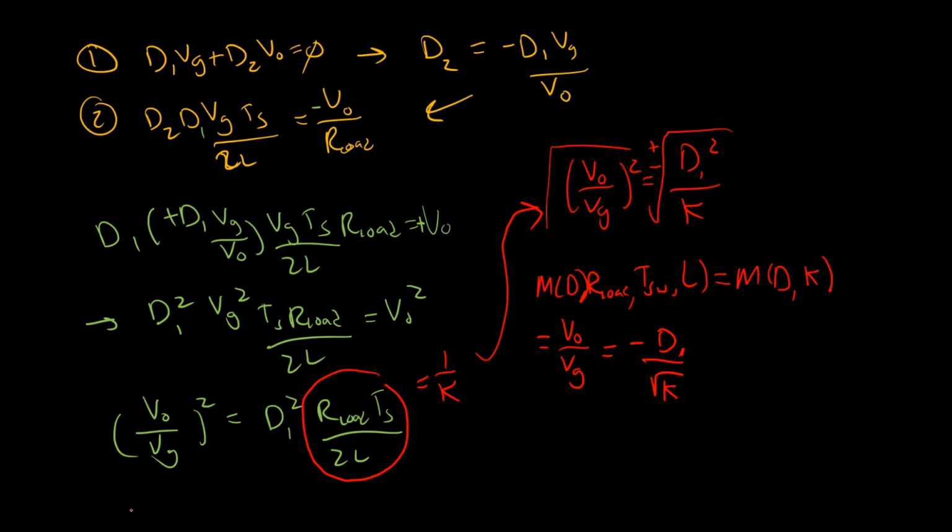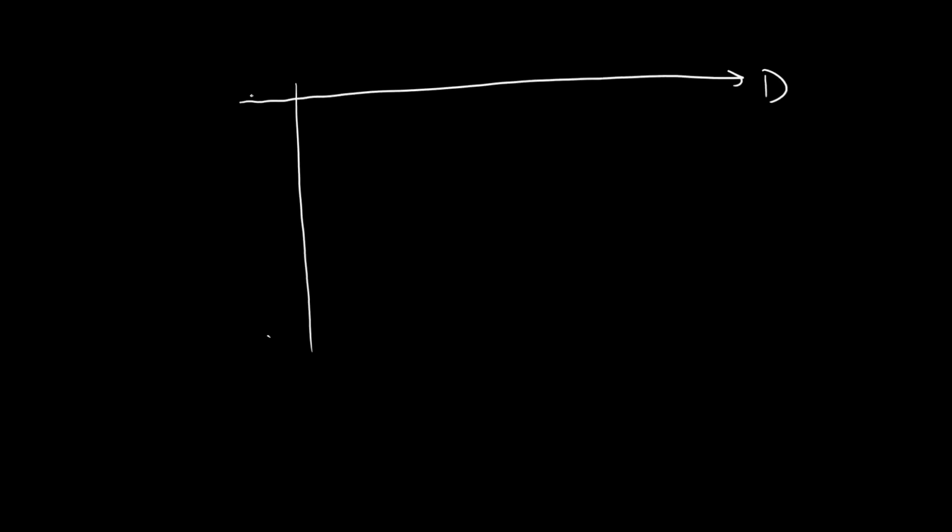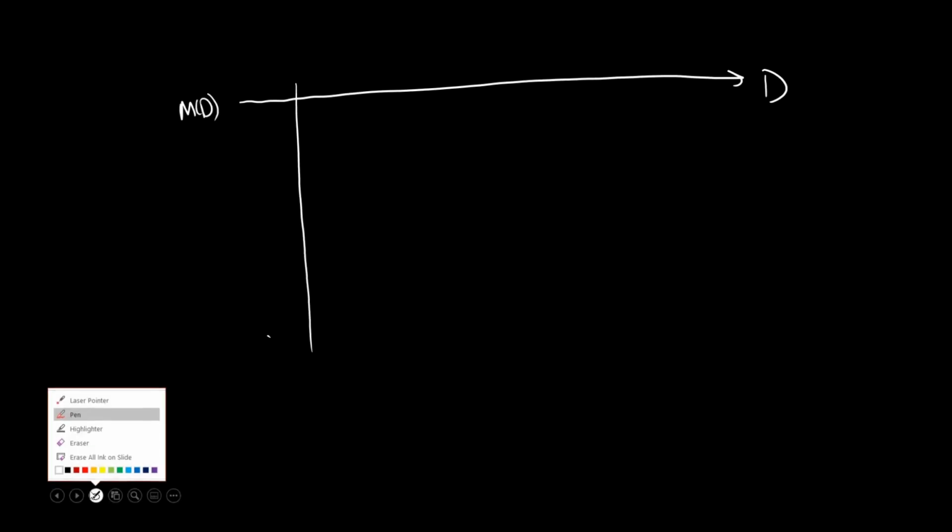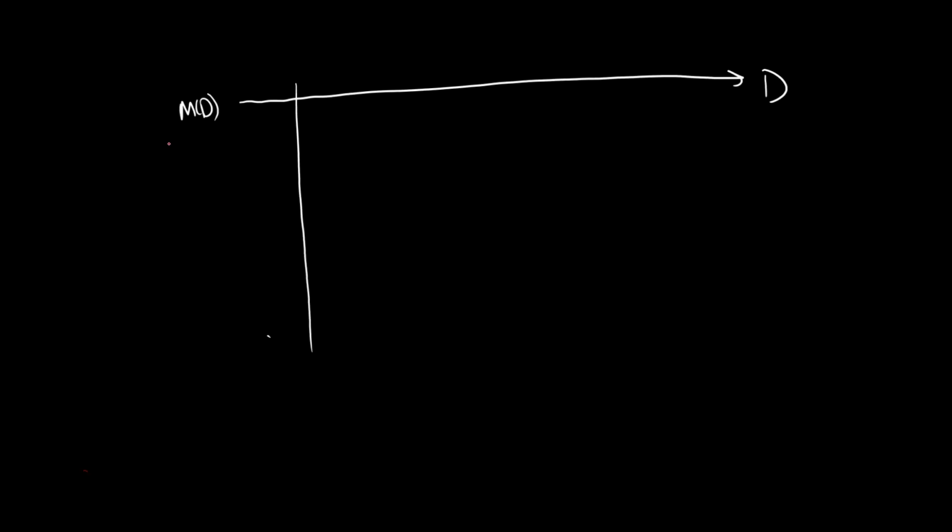So this is kind of surprising. This is a little bit surprising. We ended up with this linear function now. So what does this look like? Let's just do one final plot. So the conventional conversion ratio, I'm drawing it like this. This is d. This is m of d. Will be in white. And then we'll draw m of dk, which is like the DCM conversion ratio in red. And yeah, let's do it.